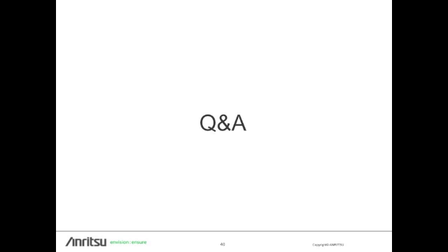Thanks. Next question we had come in. Does Anritsu have any spectrum analyzers that use FFT to improve resolution for interference hunting? So it turns out all of our handheld spectrum analyzers automatically use FFT when in one of the normal sweep modes. I actually have a way to make it not do FFT, but that's very unusual. This helps speed up the process of doing the resolution bandwidth filtering and makes the sweep times much faster.